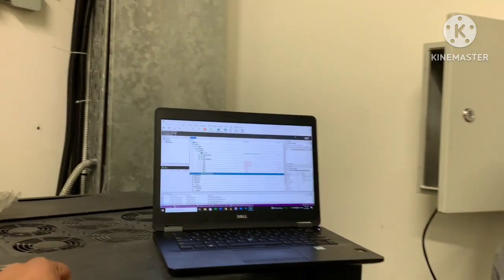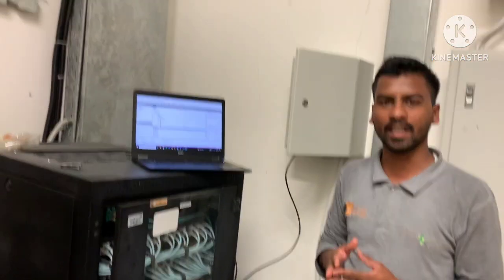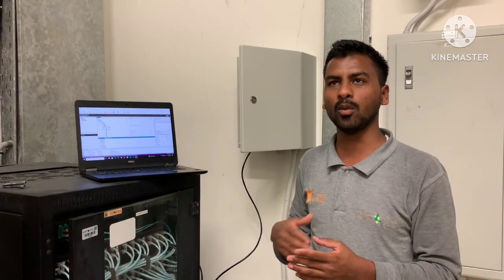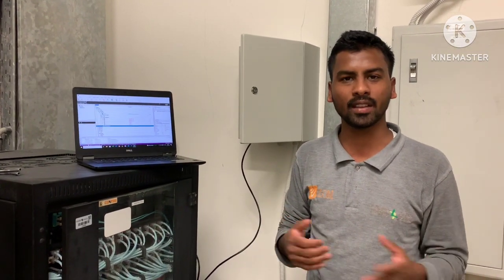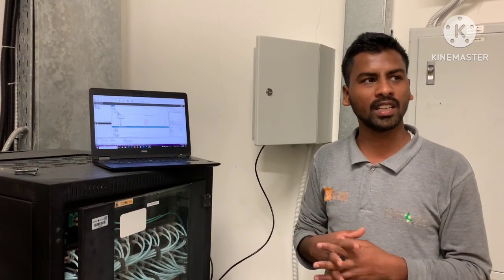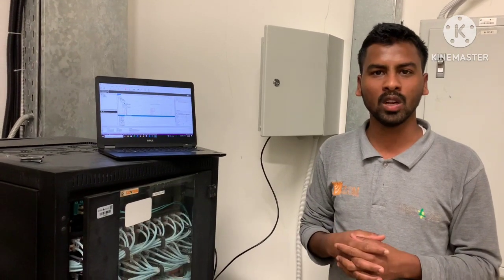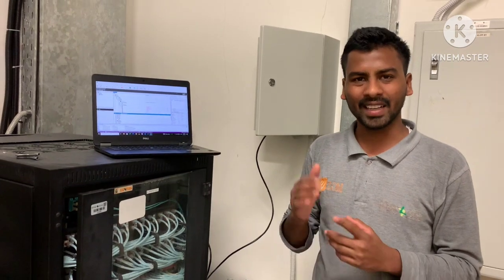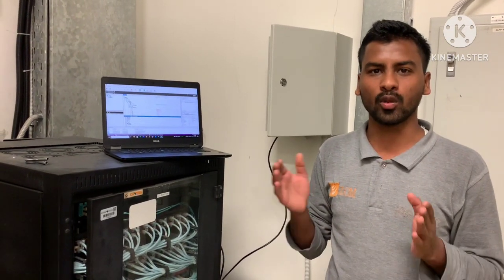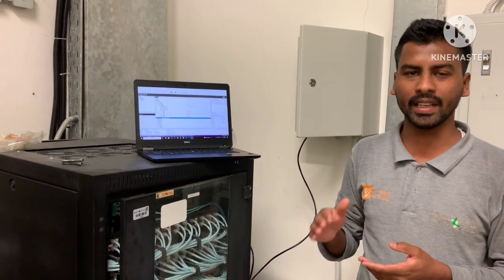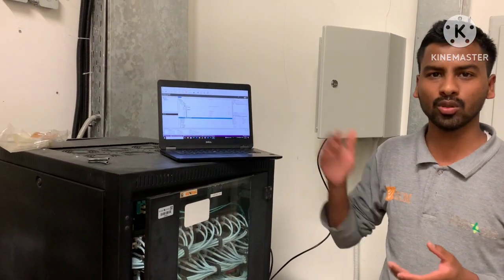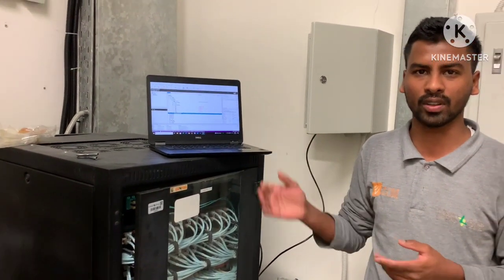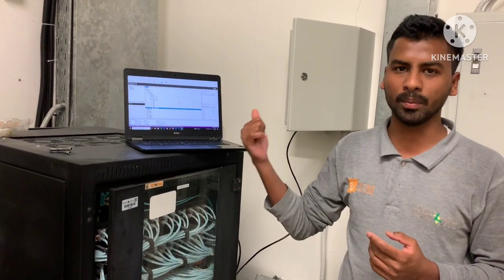So in this video, I showed you how we can integrate a Modbus device. Any Modbus device. In my case, I have used a meter that belongs to the RISH LM 1360, the model number. But in your case, any device which supports the Modbus protocol, you can integrate to the BMS, and you can also read from free software from the CAS. So you can read from there and from the BMS also.